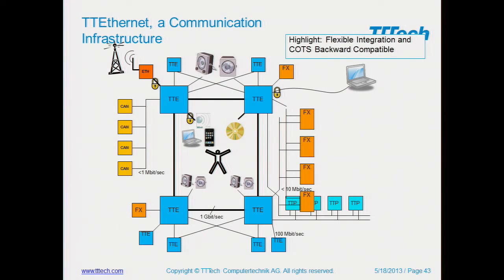So you can have parts that are a CAN network, for example, for communication of low-importance nodes in the network itself. There are, for example, TTP FlexRay slots, which are safety-critical elements, and you have TTP buses that can be attached to it. So it is a heterogeneous way of combining any kind of protocol you can dream of with an infrastructure that is extremely well-performing and extremely cheap.